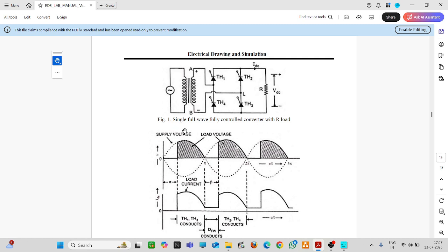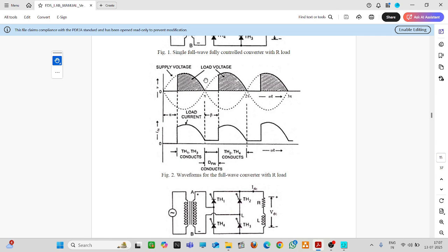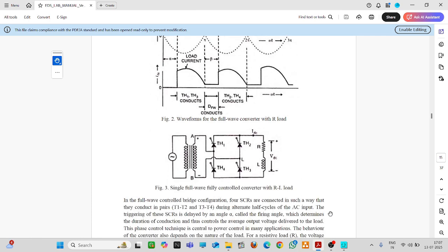And again, there is a step down transformer. In this case, an isolation transformer has been used. You can see the number of turns on the primary and on the secondary are equal. When such an arrangement has been done, you can term this the isolation transformer. Basically, it is used to isolate the input side from the output side. It means that you have taken SCRs of low value ratings. So we will try to simulate and then we'll come back to this PDF for verification.